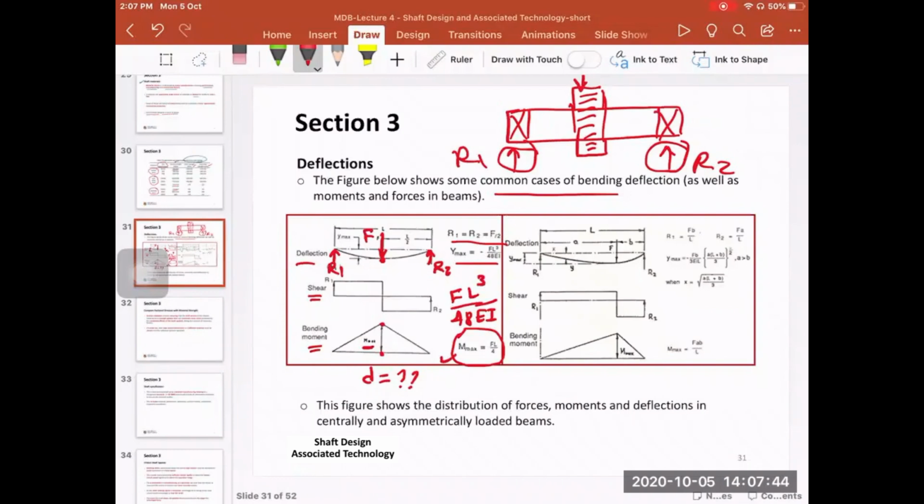And also if there is torque, the torque normally is uniform across the shaft. So at any point we have the same torque value. We use the torque, for example, based on the power that is transmitted divided by omega. And then this is the maximum bending moment. And then we take these two values, go back to our failure criteria, either the first one, the distortion energy theory, or the second one, the maximum shear stress theory, and then substitute these values into those theories.